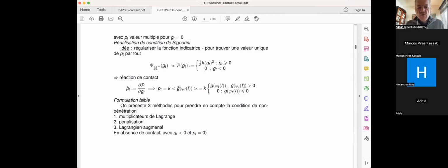Of course, what you don't get perfectly is this constraint on non-penetration. And if you've poorly chosen your K, the stiffness of the spring which is resisting penetration, then you can have a very large penetration. So people initially used Dyna3D to compute crash tests and so on. And you can see a car entering a couple of decimeters inside the wall, which is certainly not realistic. You wonder how the results can be reliable.